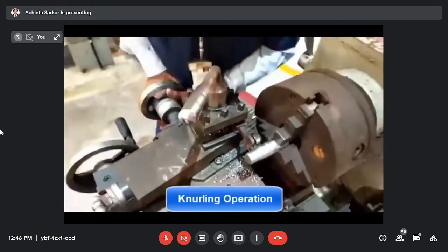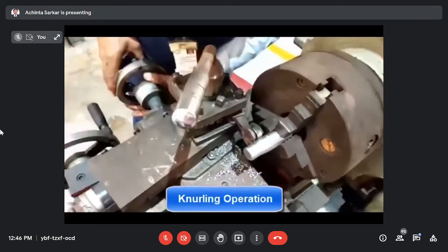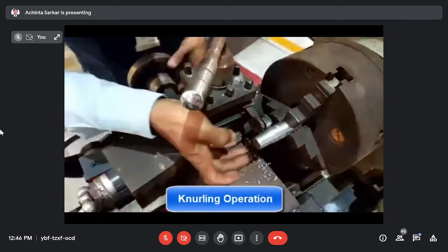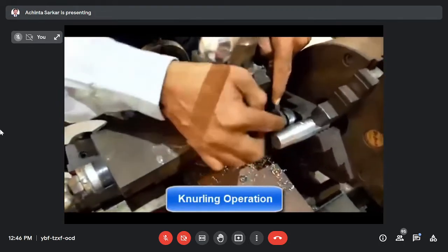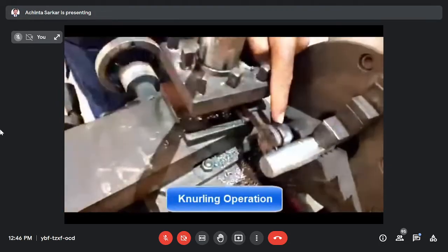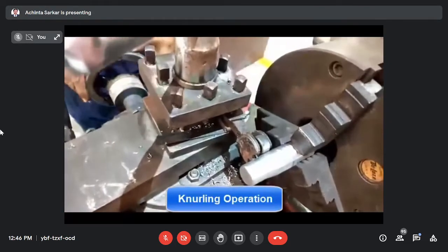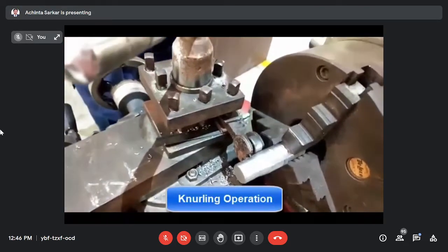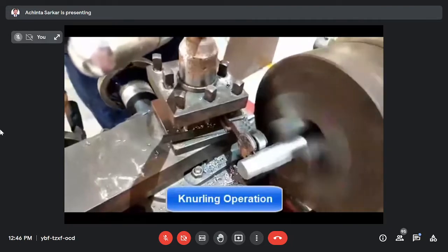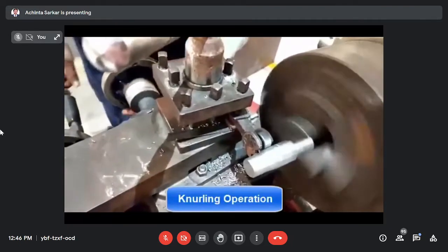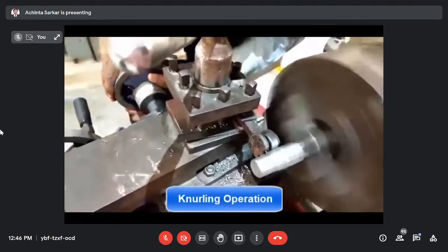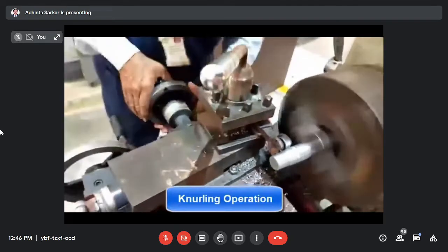First, set the two rollers at a proper center, up and down. The bottom side roller and the upper side roller should both touch the surface of the workpiece. Just touch, then start the machine, and the two rollers will be rolled. Then press again.